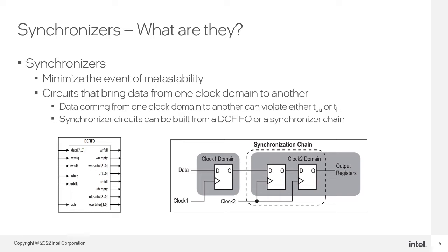Dual clock asynchronous FIFOs are popular to use to cross clock domains. The FIFO logic uses synchronizers to transmit control signals between the two clock domains. Then data is written and read with dual port memory. Intel offers a DC FIFO IP core for this operation, which includes various levels of latency and metastability protection for the control signals.